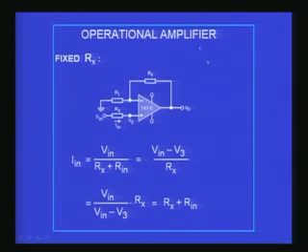Now in this circuit, what is the current I in? I in is V in divided by the total resistance. The total resistance is Rx plus R in, which is the internal resistance in which we are interested. So V in divided by Rx plus R in is I in. It is also equal to the difference between the two voltages at the ends of Rx, V in minus V3, divided by Rx. The change in voltage divided by resistance gives the current through the resistor. This is also a simple expression of Ohm's law.